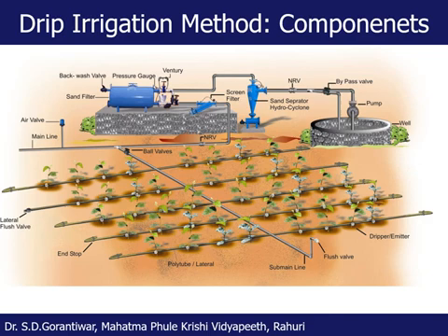For that, a certain diaphragm arrangement is made inside the PC dripper, for which we have to pay extra. The cost of a pressure compensating emitter is more, and at the same time we need extra care because of that diaphragm; we should have a very effective filtration system. Otherwise, if by chance clay particles enter the PC emitter, then the diaphragm will be damaged and this PC emitter will no longer work as a PC emitter. So in short,